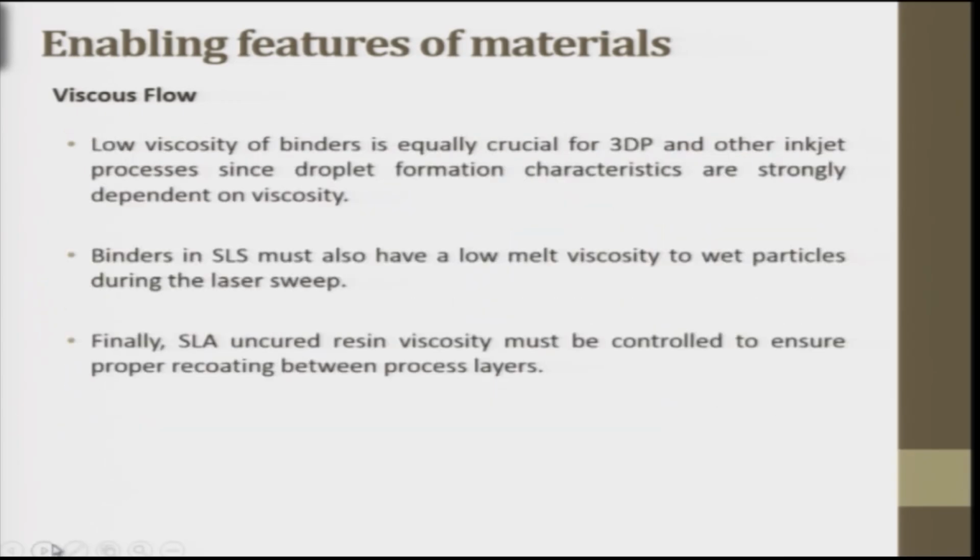Low viscosity of binders is crucial for 3D printing as well as other inkjet processes, since the droplet formation characteristics are strongly dependent on viscosity. Droplet formation happens in certain processes like 3D printing, and there are certain defects like balling effects. I will discuss the defects.